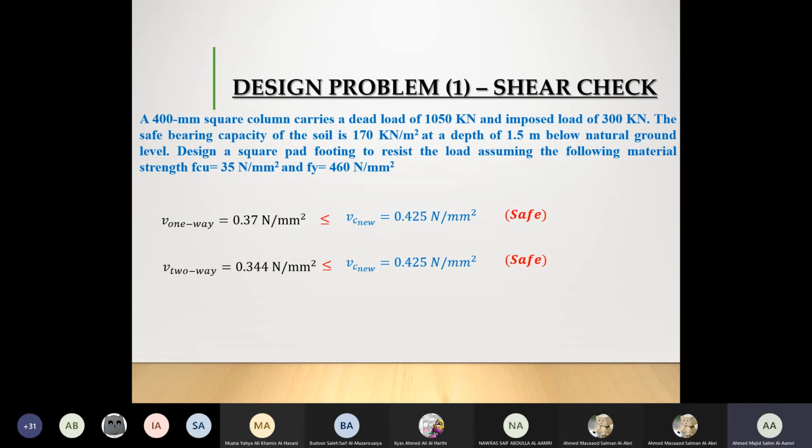The same thing for the foundation. When you increase your reinforcement, you will have to increase it everywhere. In that scenario, you will be increasing the reinforcement for a larger area. True, you will be increasing the concrete for a larger area as well in both scenarios, but the concrete is cheaper than steel. So normally the preference goes for increasing the depth. Are we clear? Yes, thank you.